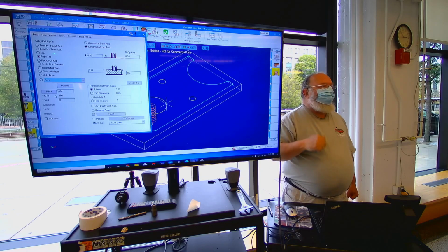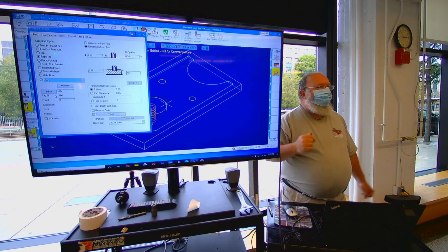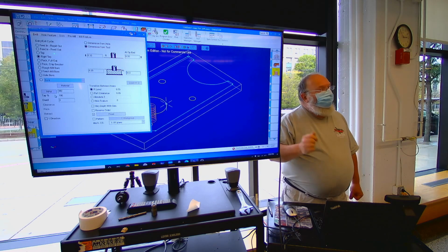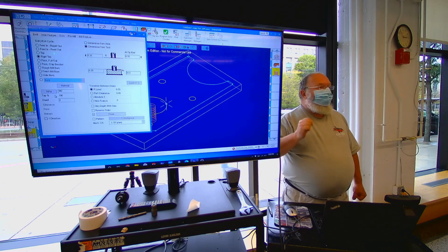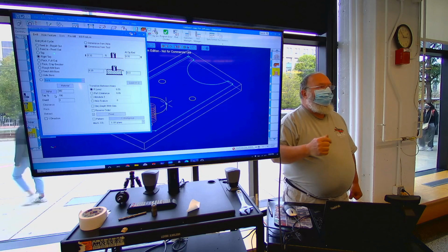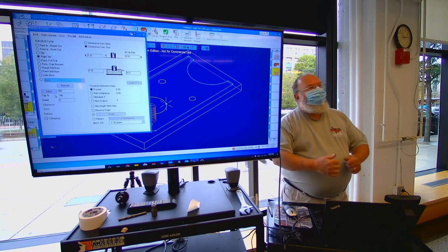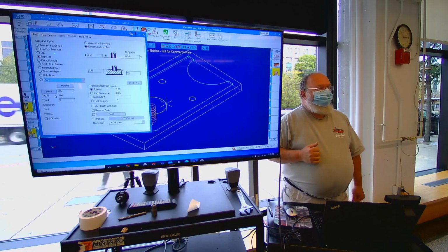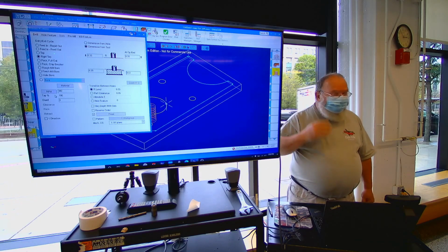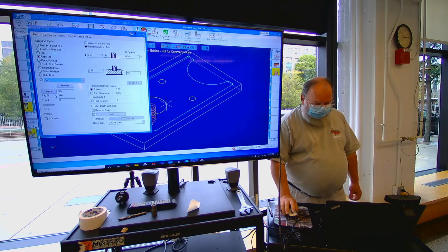All right, so now we're stopped at the bottom of the hole. Now what has to happen? We've got to get the tap back out again. So we're going to spin it in the other direction at twice the RPM and twice the feed rate and match the ramp up to get it out. Like I said, I'm pretty simple, but to me, that's an electronic miracle.